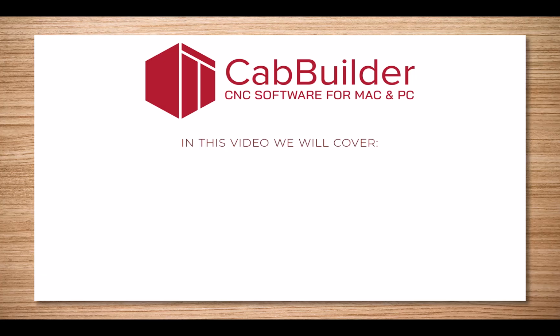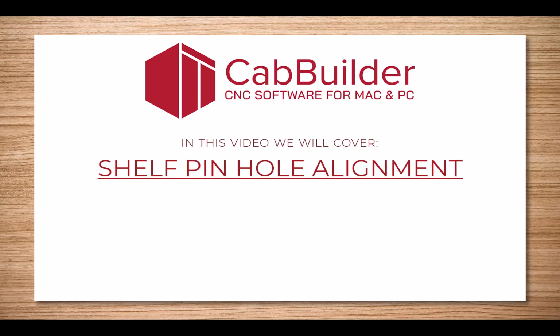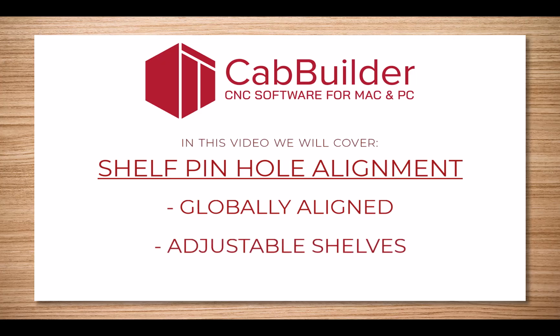In this video, we will see how the shelf pin line boring holes can be globally aligned. This will allow holes in different cabinets or with different opening sizes to be set at the same height so that our adjustable shelves will be placed uniformly.